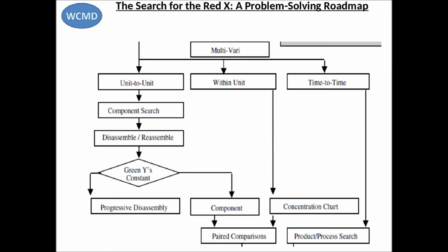Full factorial DOE is to select two levels for each factor, a high level and a low level. Then each level of each factor is tested with each level of all the other factors, creating a 2 to the power n matrix or 2 to the power n combinations. If there are 4 factors and 2 levels for each factor, there are 2 to the power 4 or 16 combinations, which means 16 experiments.